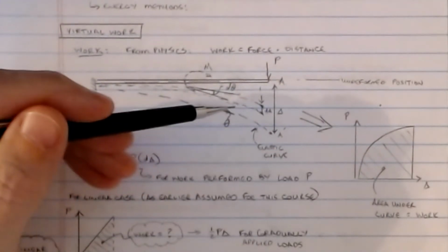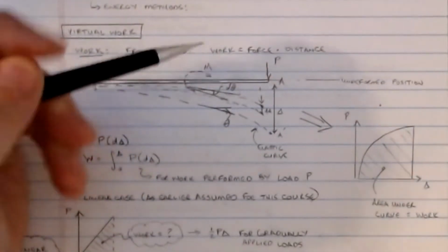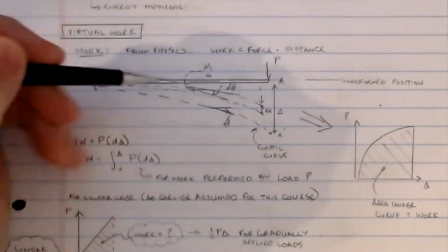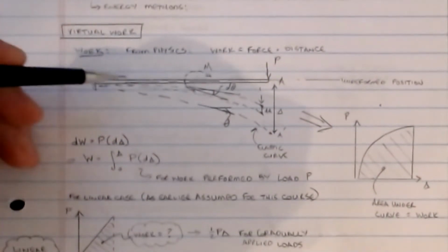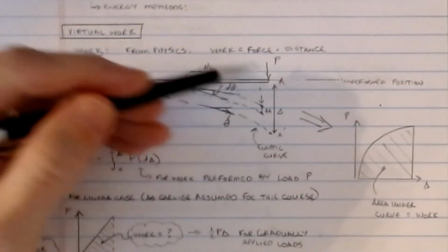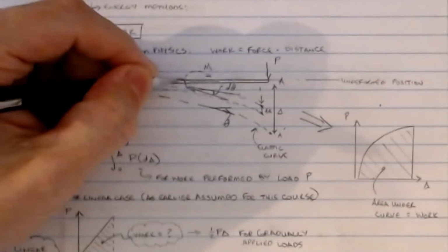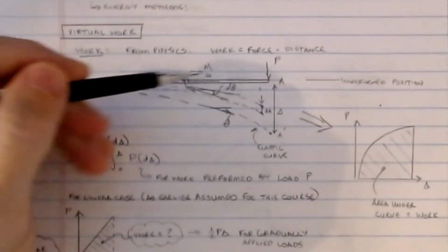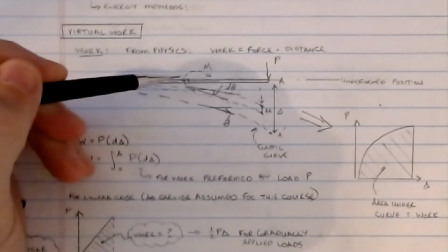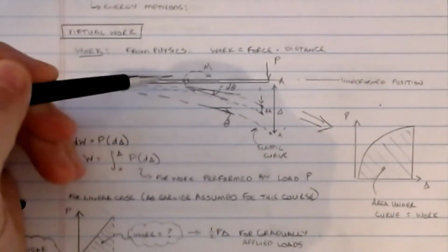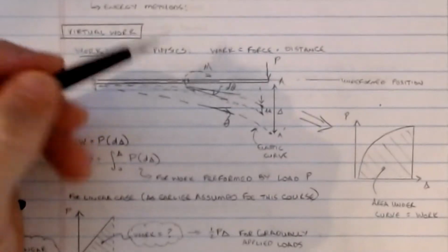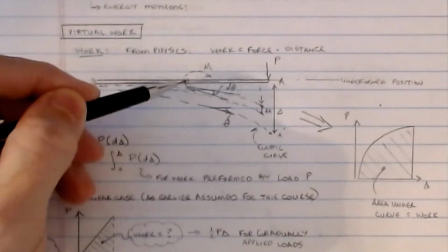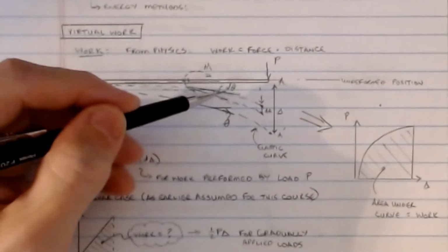Now, there are a lot of little sublines that happen in here. Every point along this beam has a moment that exists as a result of this applied load. So if we look at some arbitrary little piece, say here in the middle, we could determine the amount of the total moment applied on that little piece, because it's the moment that causes the flexing of the beam, which causes this displacement to occur. And that moment will cause a rotation in the amount of, say, d theta.